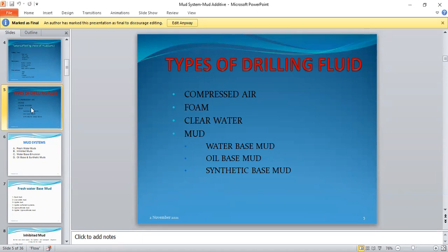a compressor that can give you enough pressure. As you're drilling, the compressed air will be blowing out. It will go through the bit, just like the mud goes through the bit. It will go through the bit and be blowing the cuttings out to the surface. And of course, there will be collection equipment. There will be collection equipment that will be collecting these solids.